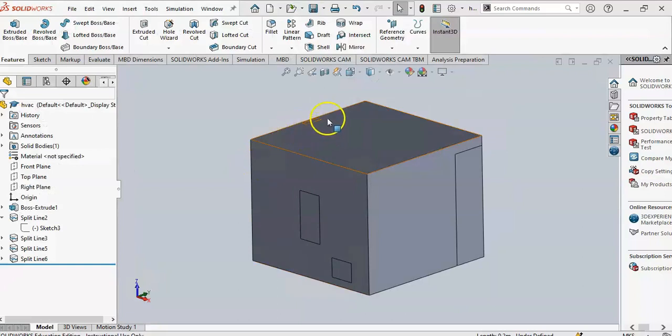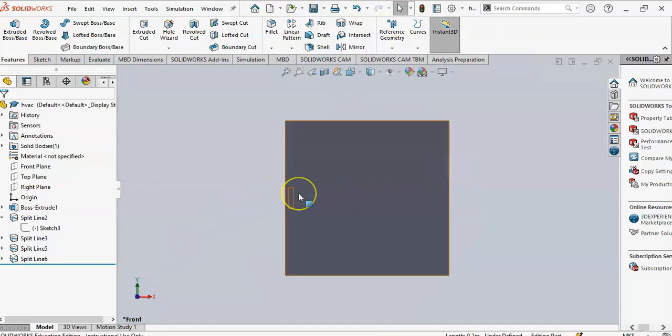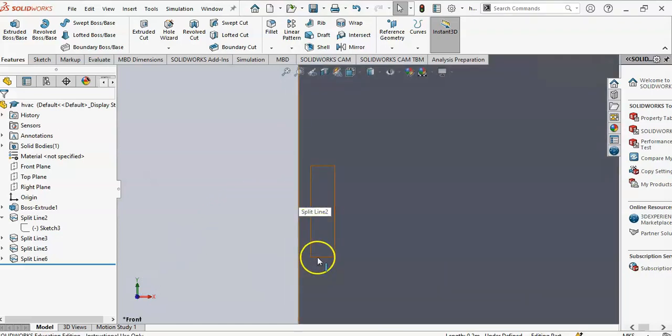One last adjustment I want to make to this, and that's to increase the size of the inlet here. That's so we can reduce the flow velocity in for the same flow rate, which will make the calculation more stable, which we'll see a bit more about in the simulation part of this exercise. So I take the view from above by clicking on the Z-axis here and zoom in on that. So I'm going to increase this from 0.1 meters to 0.2, increase this from 0.4 meters to 0.8, giving an overall increase in the area of a factor of 4.